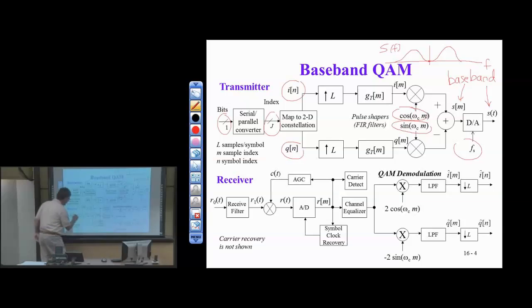And so along the signal path, we're taking this received signal, r0(t), and doing certain processing steps on it, until we get out an estimate of the in-phase symbol amplitude and the quadrature symbol amplitude. And then from there, we can make a decision at the very last step as to what bit pattern was most likely to have been transmitted.